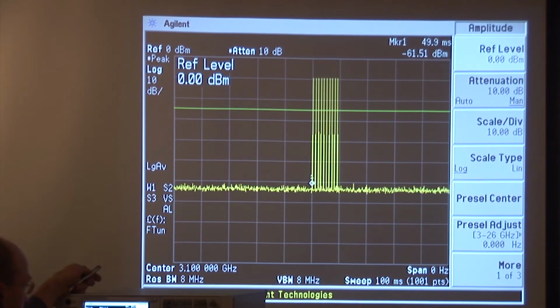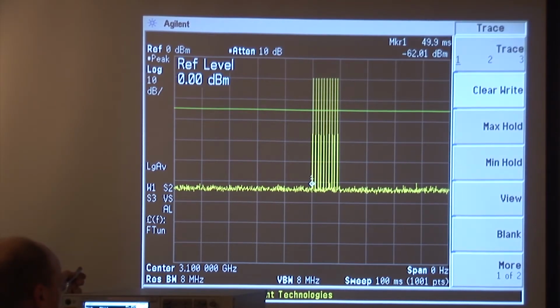Single, all right, there we go. There, the reference level top is 0, so we're measuring minus 10 dBm plus just a little bit more. And you know what that little bit of extra is? Just that extra fraction of a dB, that extra half dB, that's a little extra energy off on the sides of that lobe getting in here. But basically, we're measuring minus 10 dBm right there. Now, I'm going to go ahead and save that view, trace to, clear right.